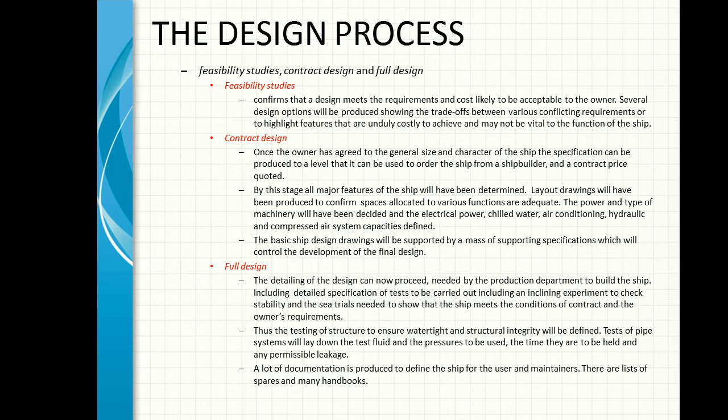The basic equipment like the power estimate, the engine types, the various facilities on board would have already been defined. Because at this point of time, the shipbuilder will have to talk about cost, and the costing calculations have also to be arrived at and agreed on at the contract design phase.